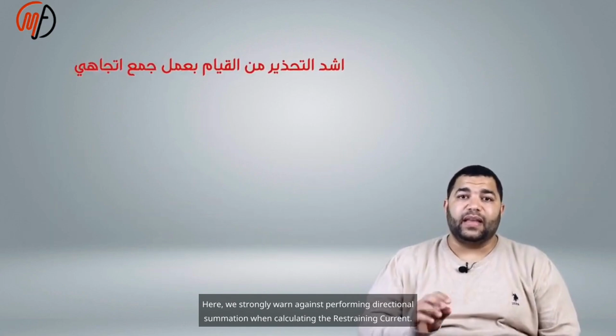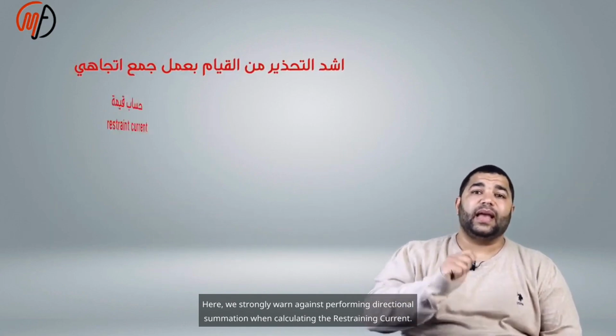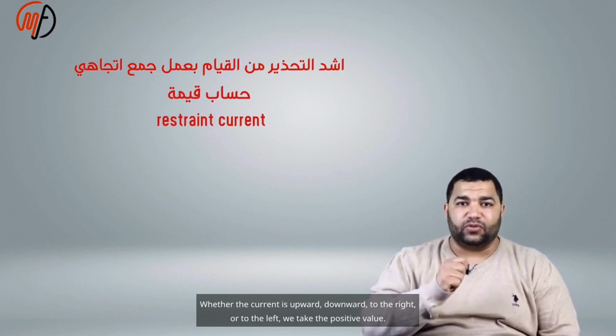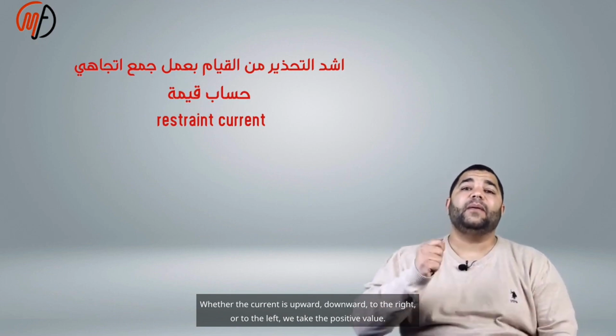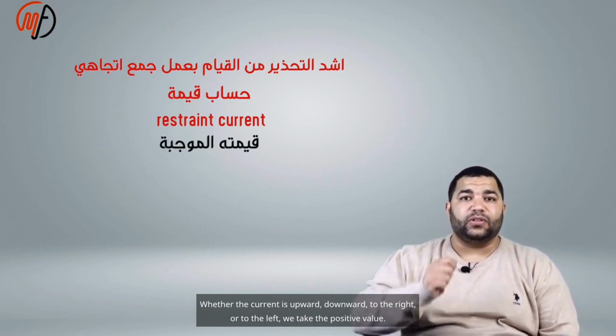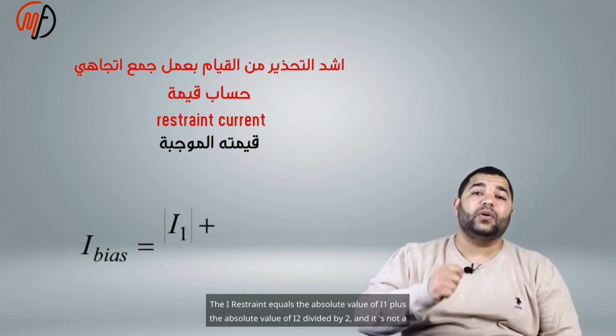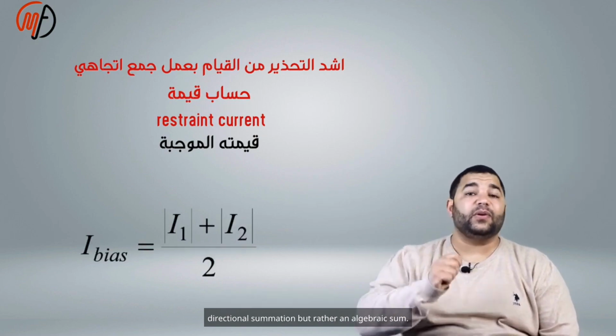Here we strongly warn against performing directional summation when calculating the restraining current. Whether the current is upward, downward, to the right, or to the left, we take the positive value. The I restraint equals the absolute value of I1 plus the absolute value of I2, divided by 2. And it's not a directional summation, but rather an algebraic sum.